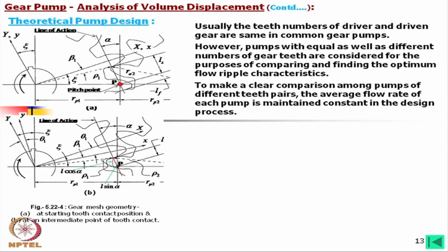If you go for very high speed, then very high frequency noise will be there. Again, of course, how the teeth are ground, what the casing dimensions are, how the error in center distance is, all such things will matter.